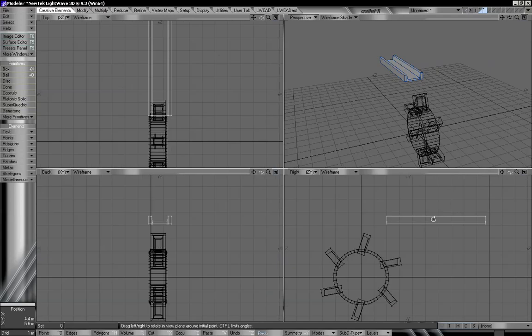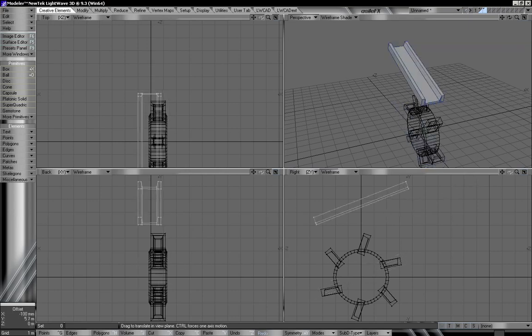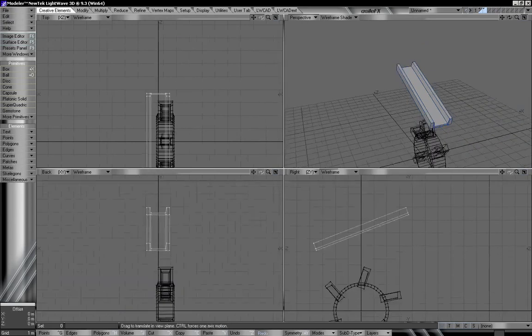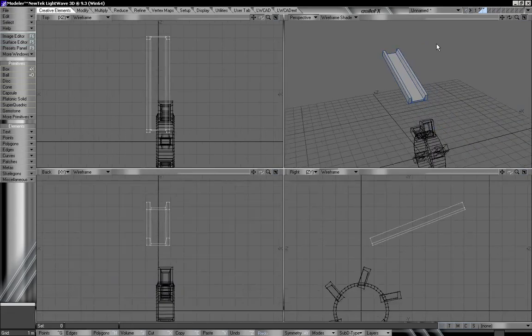And I'm going to use rotation just within the object itself and set the scene up mainly within Modeler, and that way we're not really going to have to make any adjustments to the movement within Layout. I'm going to hit F2 on the keyboard to center this, and then we can constrain this and pull it upward. And then I'll want to move that to the side.